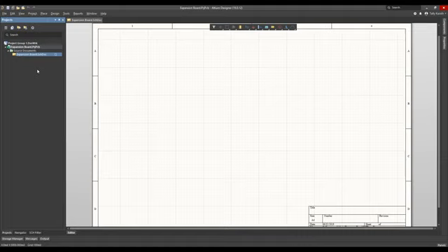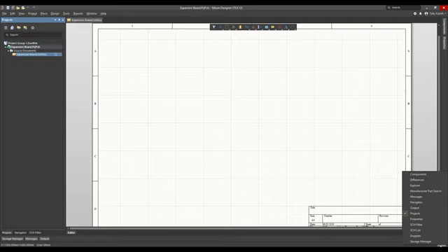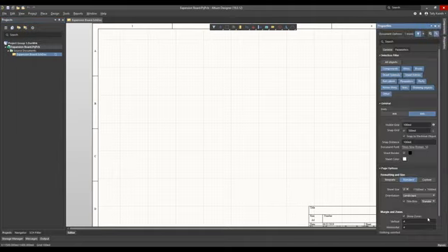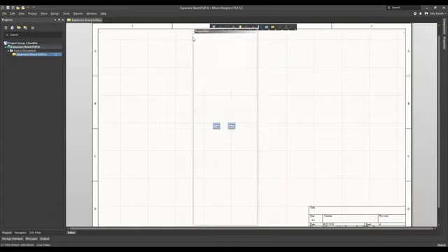To access the list of possible panels in Altium Designer, left-click on the Panels button on the bottom right of the window. This opens up a menu with the various entries. Note, the panels with the check marks are currently open. If the Properties panel is not opened, I would encourage adding it now by selecting it from the list. The window layout is a personal choice, and I would encourage you to spend some time deciding what panel arrangement you prefer. We can move the panels by selecting the title bar and dragging them.